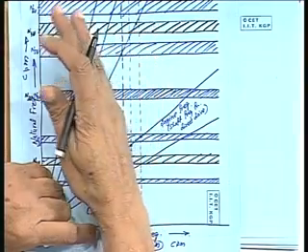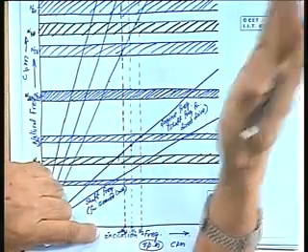Full band. So that means the overloaded condition and also say 80 or 85% of the MCR. And then you check with the upper limit and the lower limit that all these frequencies which can be generated due to this excitation are avoided.